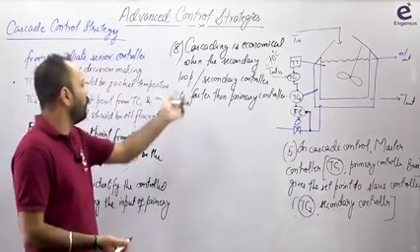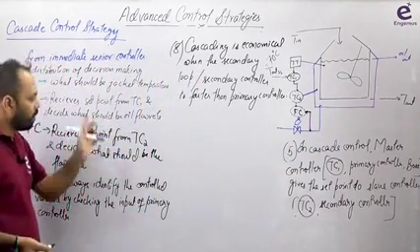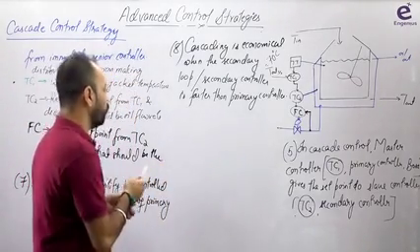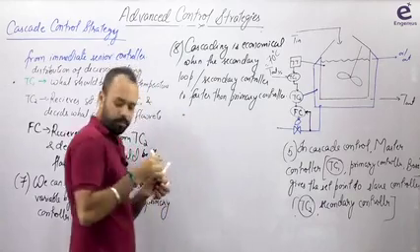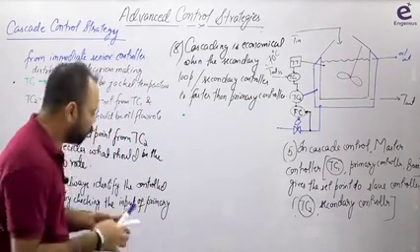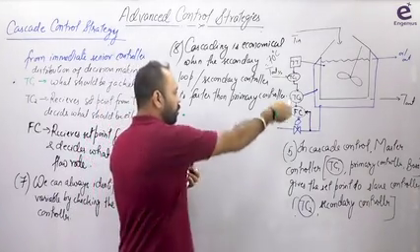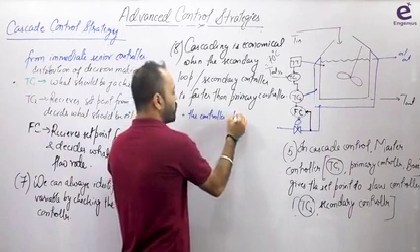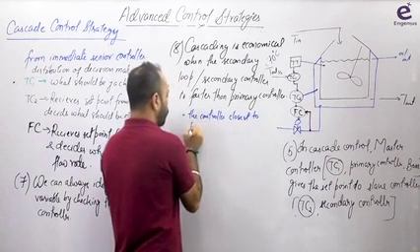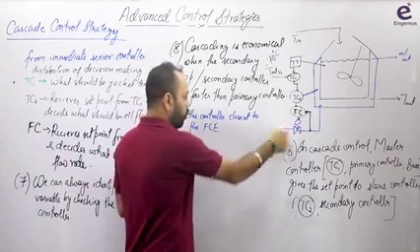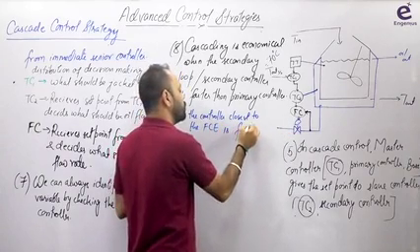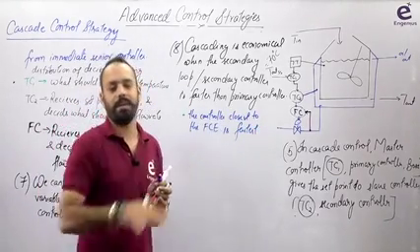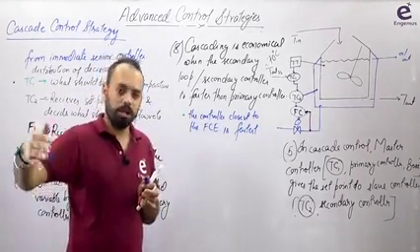So the secondary controller cascading is economical when the secondary controller is faster than the primary controller. Now in this there are some sub points also. Suppose if there are only 2 controllers, then it's okay, but if there are more than 2 controllers, 5 controllers, like that, the controller closest to the final control element, FCE, the valve, is slowest or fastest? Fastest. Because the controller which is closest to the final control element is lowest in the hierarchy position, and therefore he, or she, should work fast.